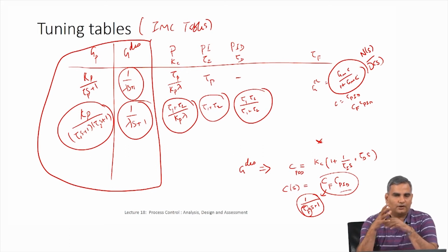However, the disadvantage with the PID controller is that because I have a derivative of an error, if the sensors measuring your outputs are noisy, then your controller will chatter a little bit. Of course, one way to avoid that is to smooth the measurement, but if you smooth the measurement, then the effect of the future actually gets lost a little bit in that process. So conceptually PID, while it sounds great, in real implementation there are issues with it.